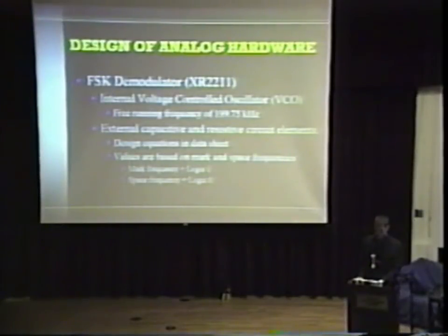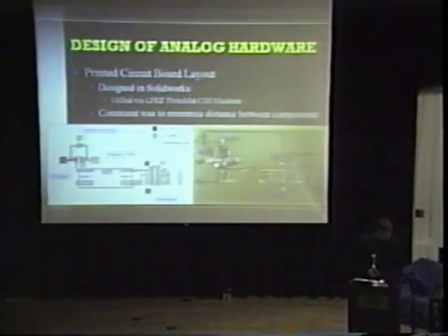And all of these equations are within the data sheet to design for these specific components. The printed circuit board was designed in SolidWorks, and it was milled via the LPKF Protomat C60 machine. The constraints here were to basically just minimize distance between components, minimize trace lengths.